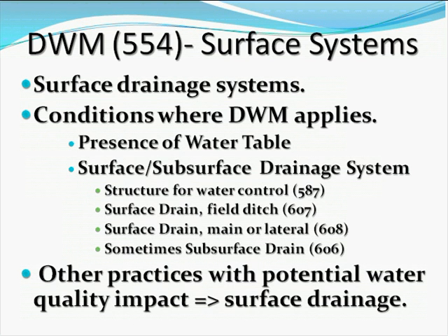Because a pure surface drainage system would generally be addressing surface runoff and not subsurface flow. And so most of the surface drainage systems you're going to run across are not systems where you would be able to practice drainage water management. Drainage water management is only going to apply when you have a water table. So if you have a purely surface system, that is just a surface system. You're not going to be looking at a water table.